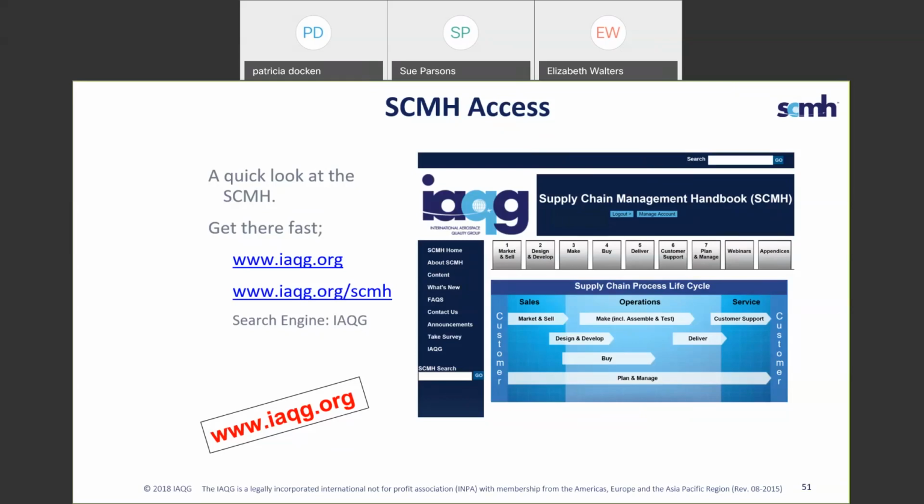You may have proofed out a product, and you don't need it on the control plan anymore. You might have done a poka-yoke and you don't need it on the control plan anymore. You take that off. But anytime you update the PFMEA, you certainly want to look at the control plan, because chances are there'll be some inspection changes on that, either added or taken off.